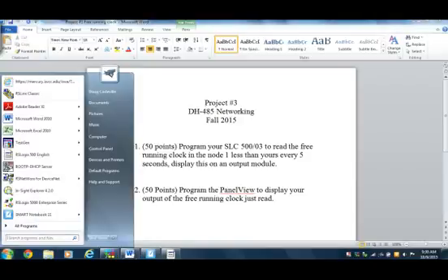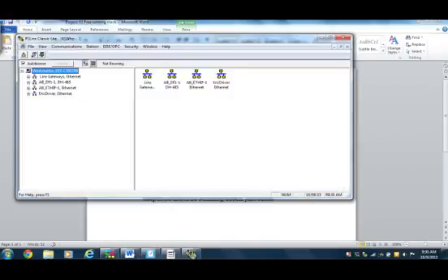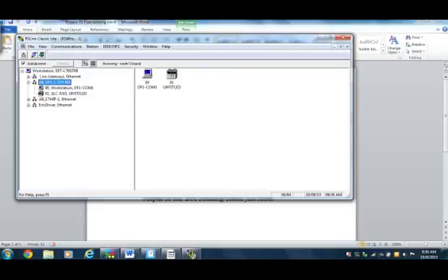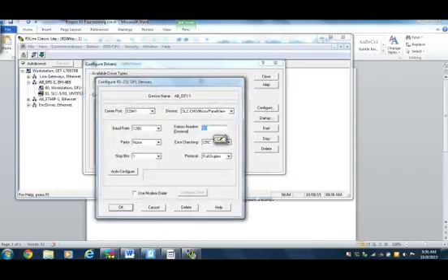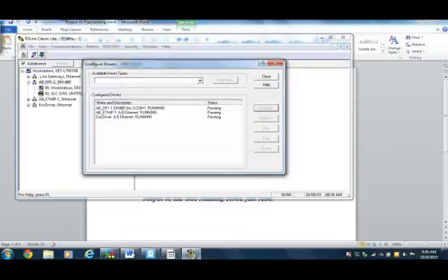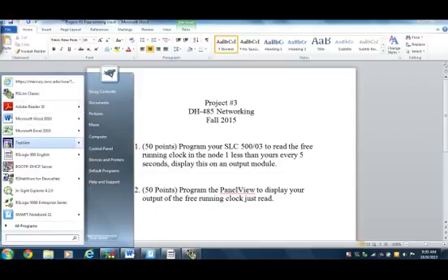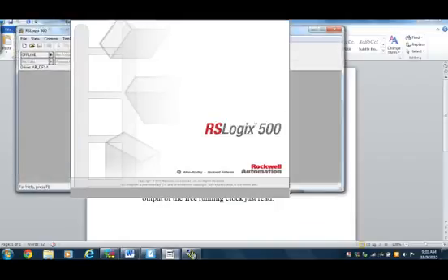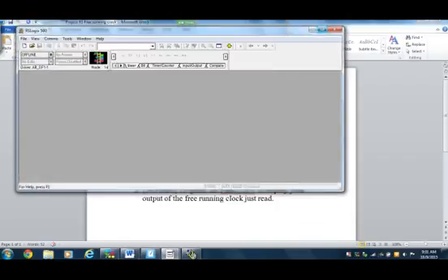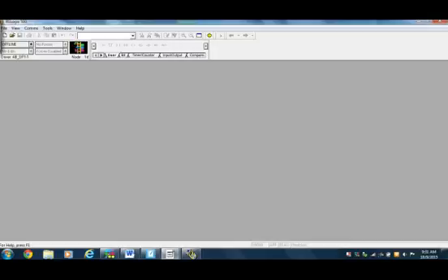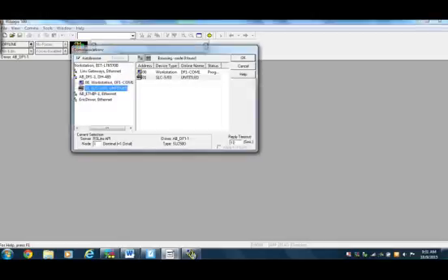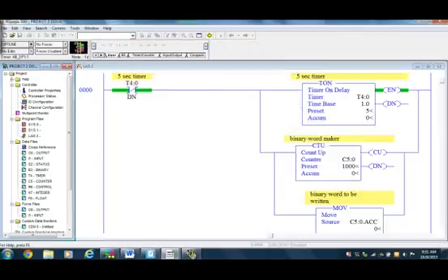First thing we're going to do is come up in RSLinx and establish communications with our processor. We come up on this wiggly line in the middle, and we do an auto configuration, and we are successfully configured. We're happy about that. We close out. We keep the RSLinx program running because it's necessary for the process. All right, in order to have communications, I have to do that. We come up on the RSLogix 500 program, which is in fact missing its icon, which is semi-disturbing. And we go to Comms, Who Active, online. We select the 01 guy, which is the processor. Because we're a DF1 serial connection, that's the only thing we're seeing.